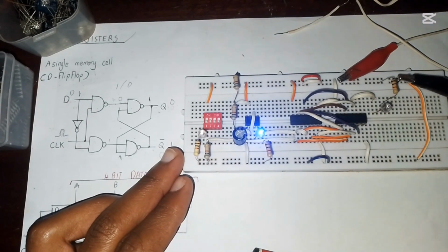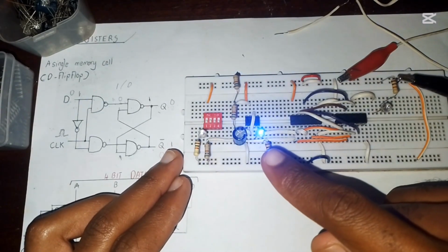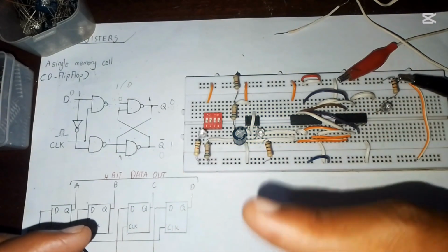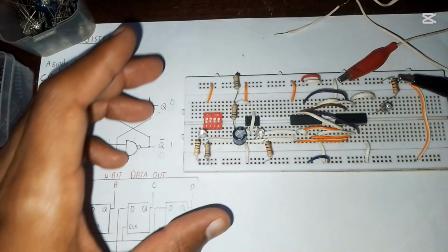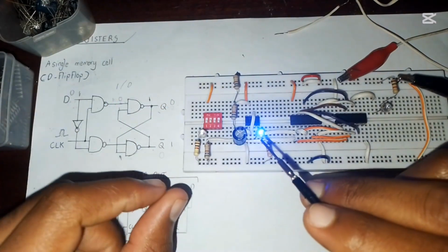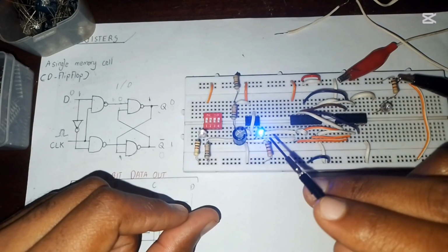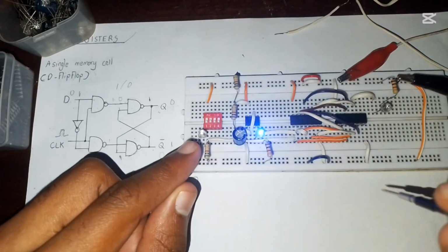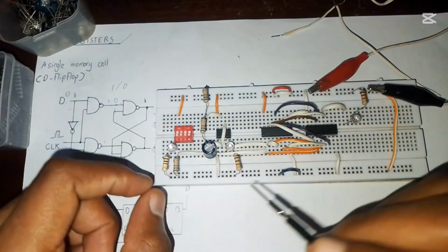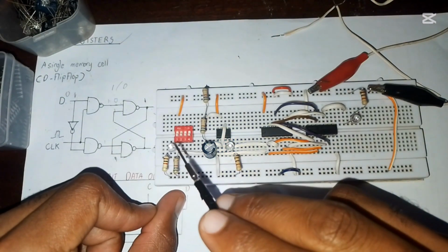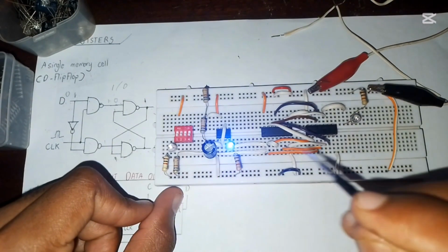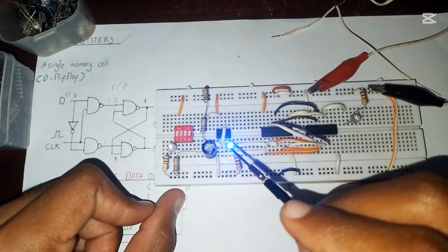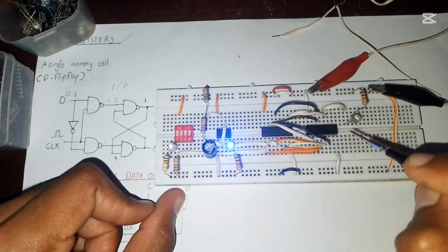So it's on, and you can see the clock pulse. It's much slower. If it were a real-time circuit, it would be blinking very fast. So we said that the circuit is controlled by this clock pulse. When the clock is high, that's when the data is going to be changed to whatever you kept at the input. So if I put 1 in the input, it will have to wait until the clock is high for it to give an output. If I put a 0 here, it will have to wait for the clock to be high in order to change what was initially in the data flip-flop.